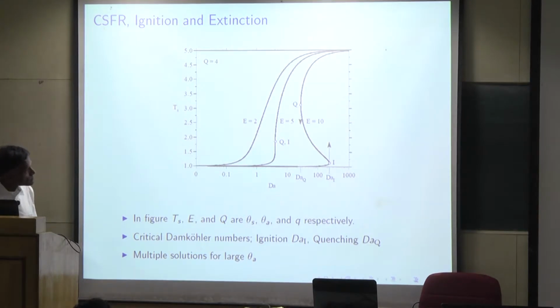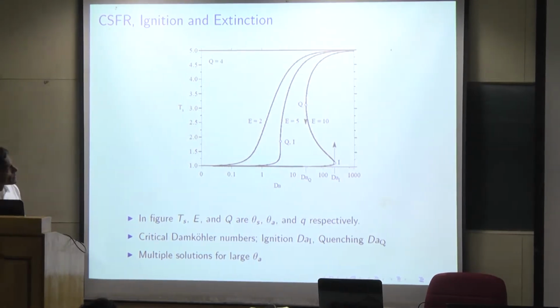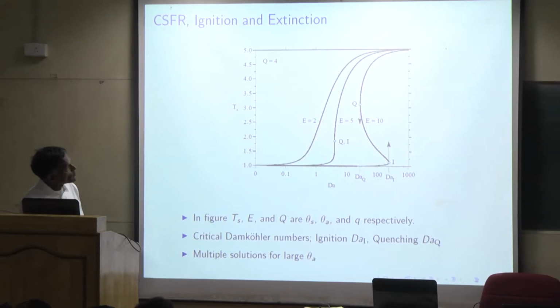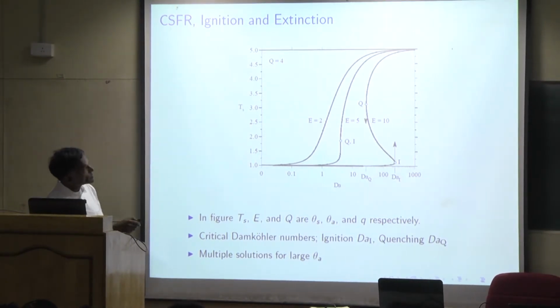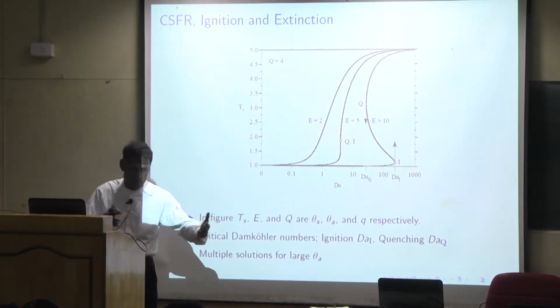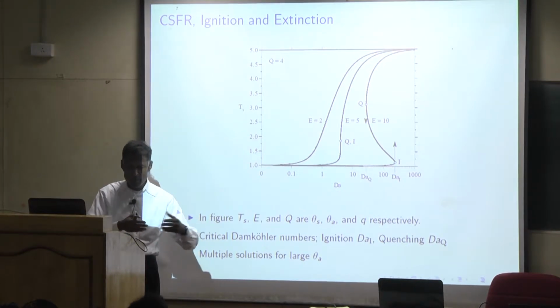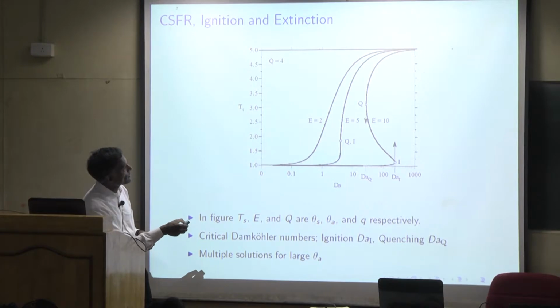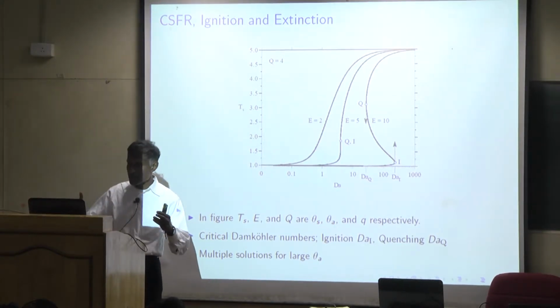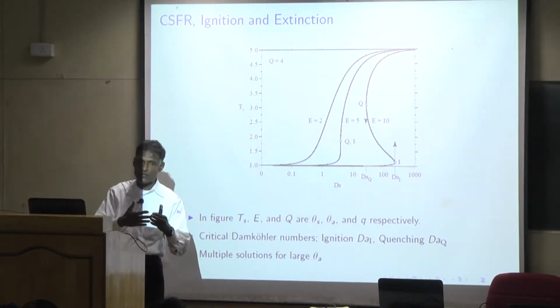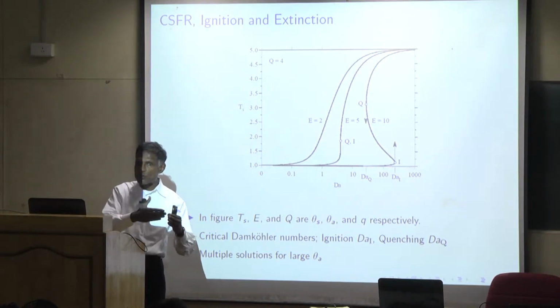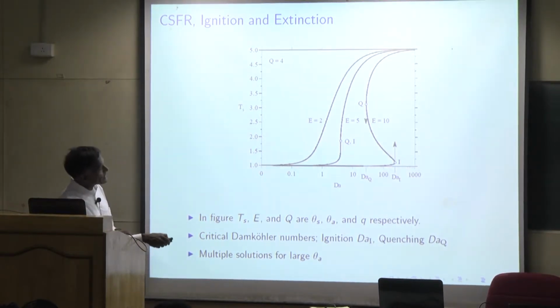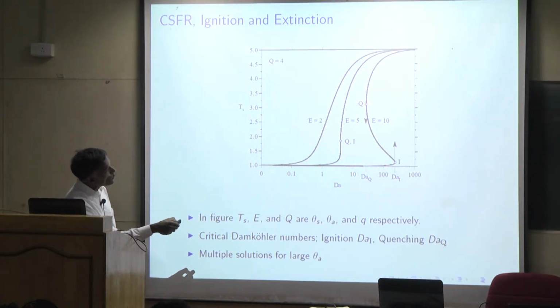Okay. So now you notice that the system is ignited. If there is a rapid conversion, and after the conversion takes place, I then decrease the Damköhler number. One way to decrease the Damköhler number is to increase the flow rates. If I start increasing the flow rates into the reactor, you can see that the Damköhler number decreases. It starts to move down this way, and when it reaches this point, it cannot continue.